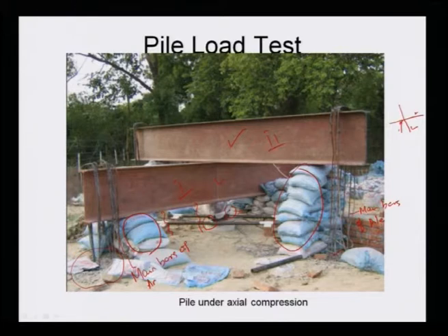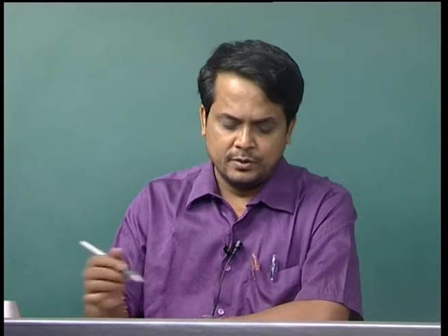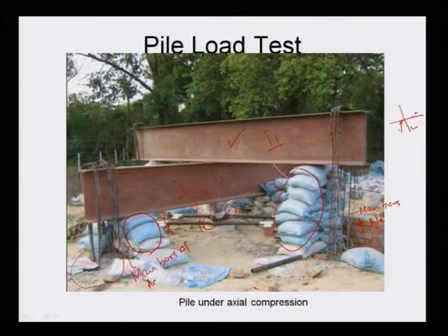This is stage 2. After you provide this, then in stage 3 you wait for some time, so that whatever displacement has been achieved by the self weight of the girder, you can leave it. This is a dead load. Then you take the reading from the dial gauges by means of the hydraulic jack. This hydraulic jack has been connected somewhere else, and here there are also some wires coming, where you can measure strain gauges, strain rate.